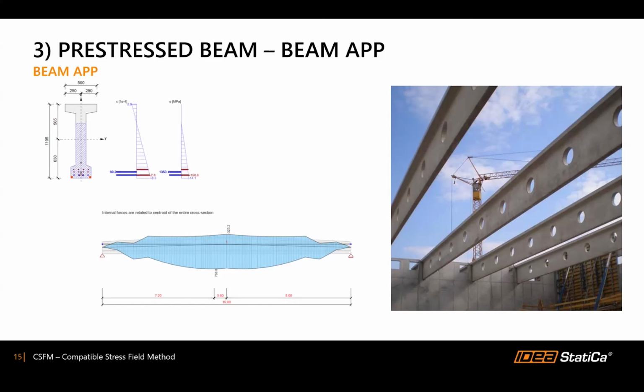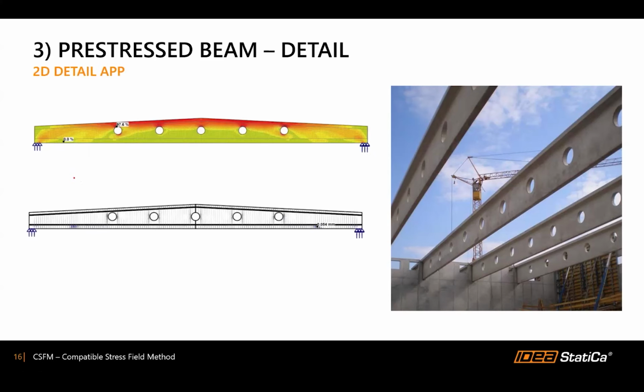Later on, we'll export this beam to the application IDEA StatiCa Detail, because there will be many openings. In a 1D model, or a model composed of beam elements, you cannot put in the openings. You need to use some more advanced approach, or wall elements, shell elements, where you can put the openings and run the analysis.